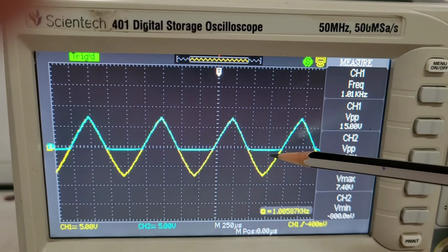The second circuit, shunt negative clipper with positive bias. The positive bias 3 volt is connected below the diode, plus DC polarity is connected to the anode of the diode, and the minus polarity of the bias voltage is connected to the common ground.